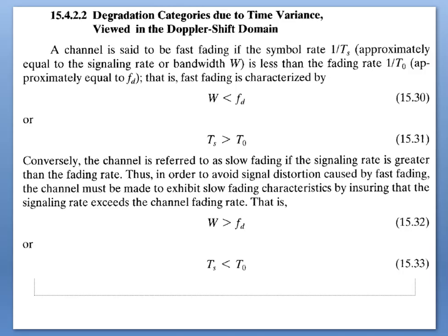For a single specular Doppler path without scatter, the resulting instantaneous frequency shift is calculated as Fd equal to V by lambda. However, a combination of specular and multipath components yields a rather complex, time-dependent instantaneous frequency, which can cause frequency swings much larger than plus or minus V by lambda. This can happen when the information is recovered by an instantaneous frequency detector.